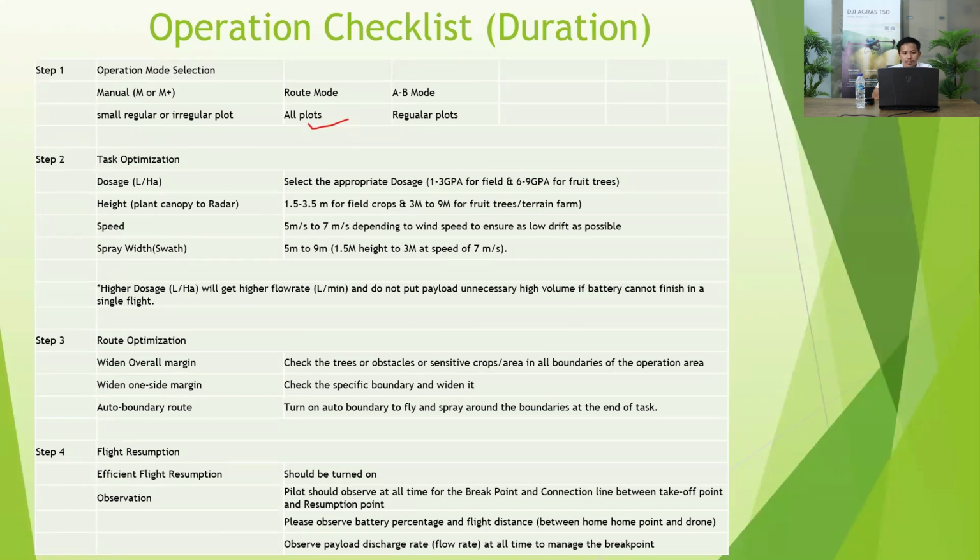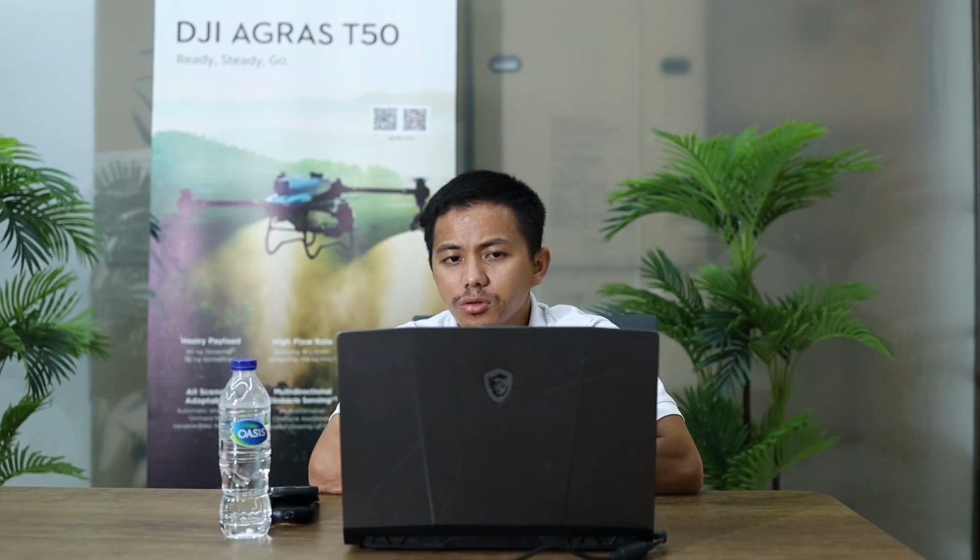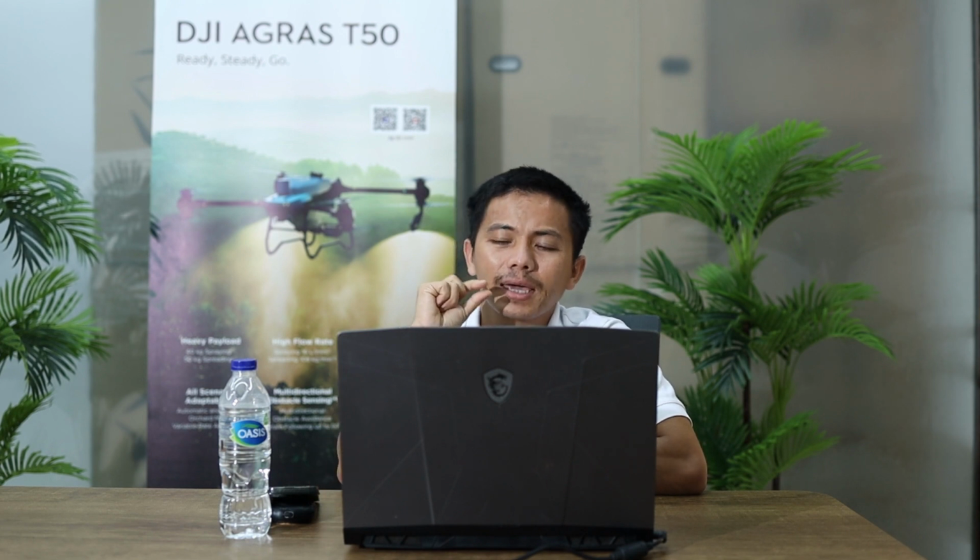And the second thing is you can check the height. For the height, it is only counted from the plant canopy, from the top, not from the ground surface. Okay, and also to the radar, so it depends where your radar is. So this is important. You need to select the height. The height for field crops is 1.5 to 3.5 meters. It also depends, and for fruit trees 3 meters to 9 meters, and some terrain farms also, because terrain follow in most drones I see is a little bit lagging.